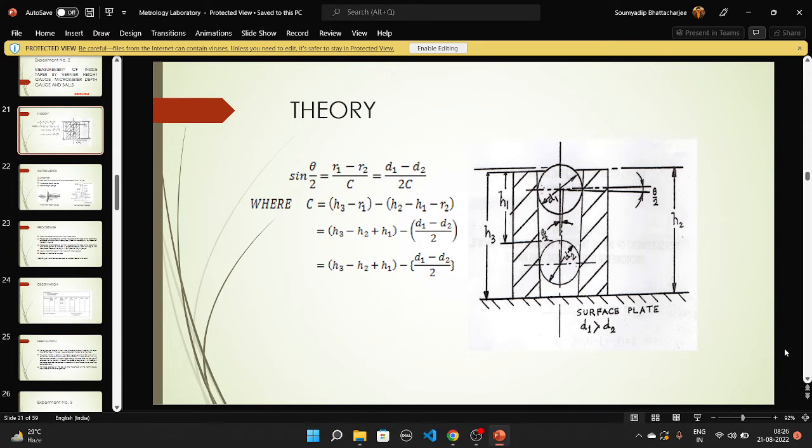Sir, then there is an extended rod length, the small extended rod that is sticking out of the micrometer face. Okay, so that you have to consider when you take the measurement, along with MSR plus CSR, along with main scale reading plus circular scale reading into LC. Yes.